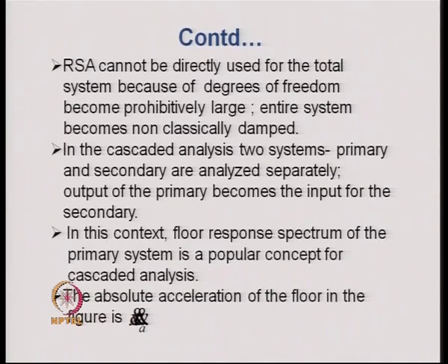Then to this time history of acceleration, we add the ground time history of acceleration to obtain the absolute time history, or time history of the absolute acceleration.